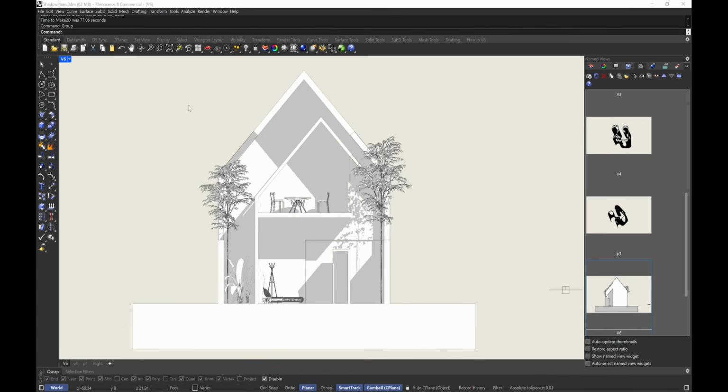Now, after I make 2D, I personally don't want these blocks on here because it creates an underlay issue, especially with really messy blocks like this bed block. Again, this is not a good bed block. This is actually a block you don't want to use. So I would hide that, for example, before I do view capture to file.